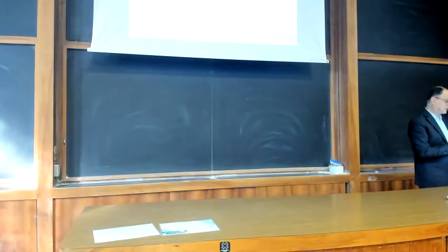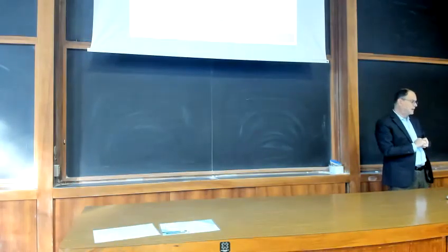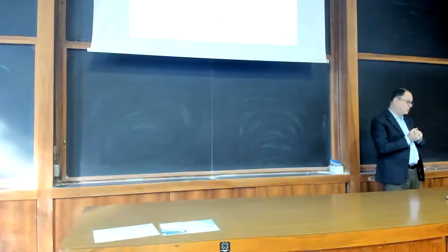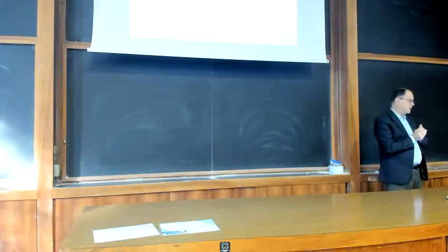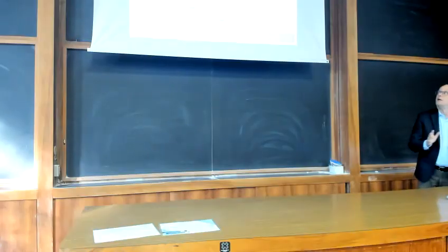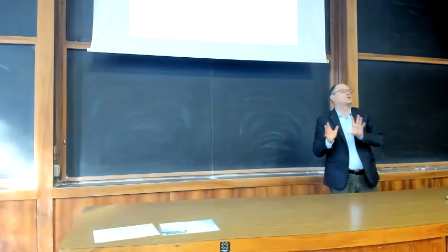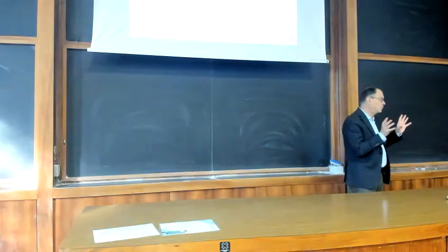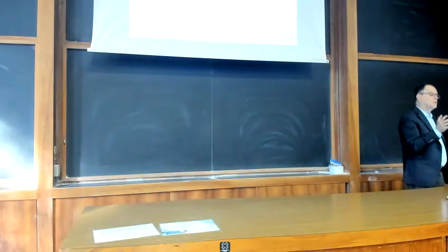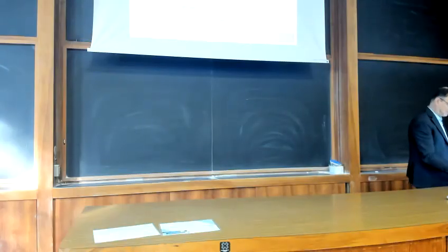The resultant pressure is located one third of the height above the base of the wall in the case of a cohesionless soil. And the resultant force is parallel to the backfill surface. So, as you see, many assumptions. Where do these assumptions come from? Why do we have to introduce them in order to apply this theory?